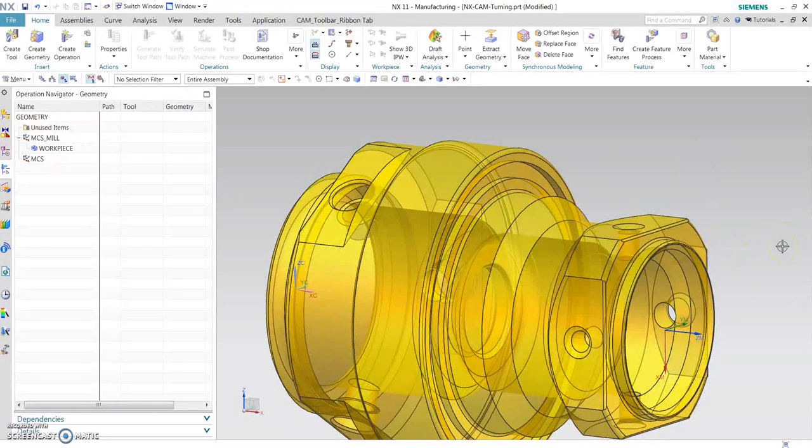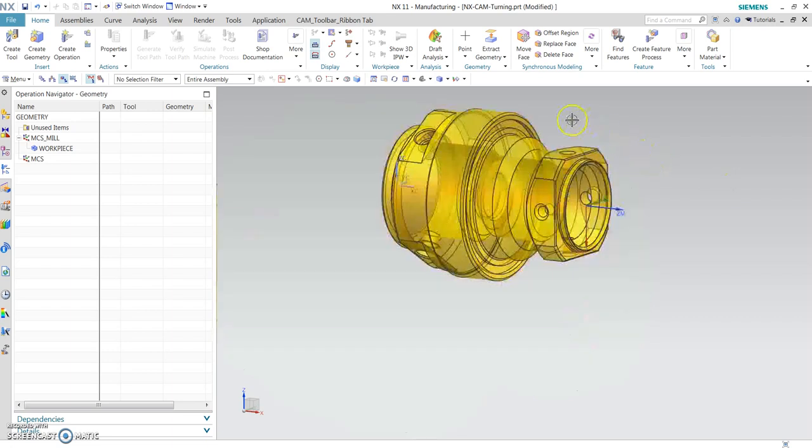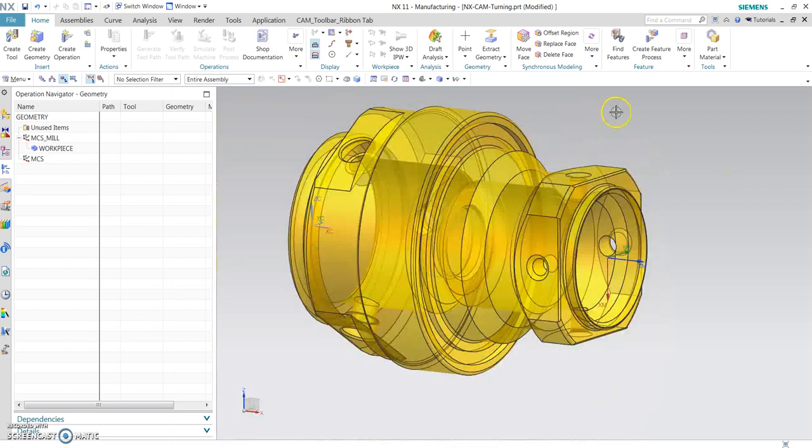On the boring bar, since we need to keep a positive rake, on the ID boring bar let's use a positive rake angle. That means instead of CNMG, we have to use a CCMT. For a finished ID boring, we'll use VCGT inserts. So we have to consider the tip of the insert, the coating, and the chip control, depending on the type of the material you're cutting. The chip control and the coating on the insert will tell you how to get the best optimum process.